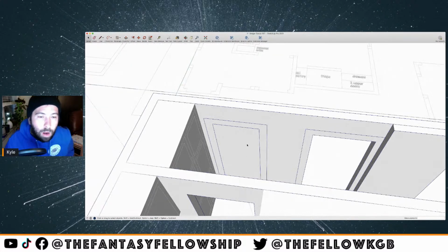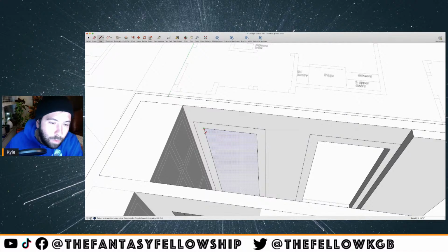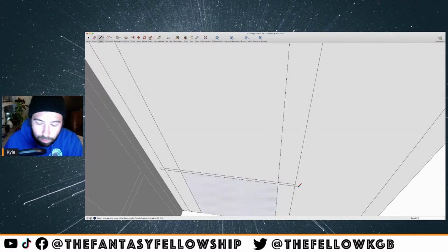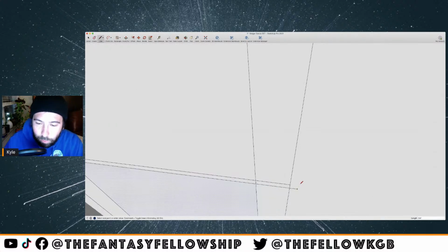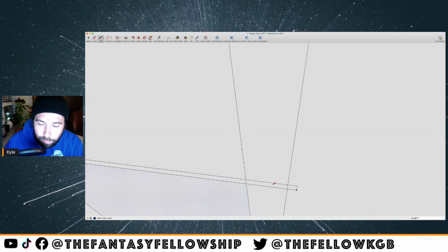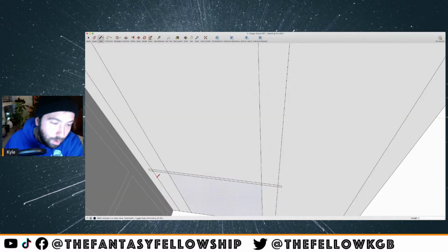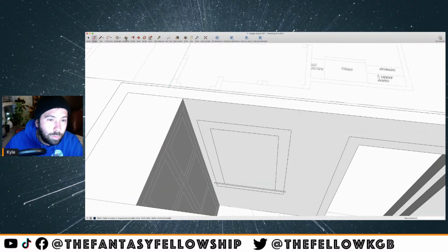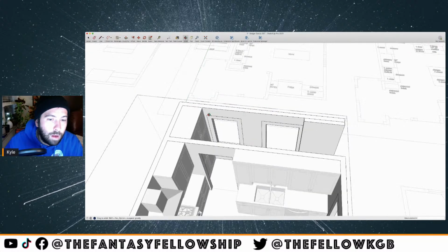It says bigger window. I'm going to click into my walls. I'm going to go at the top of the window, and let's just go down 4 feet. We'll make a window here. I'm going to add just like a little window sill to the bottom of the window. And next we'll draw a window and get that looking real for you guys, so you can see what that would look like. And then we'll just draw a little small piece at the bottom of the window here. Let's zip off some lines. And then I'm going to use that push pull tool, and let's push in the square to make the opening for the window. So cool, we have an opening for a window now.